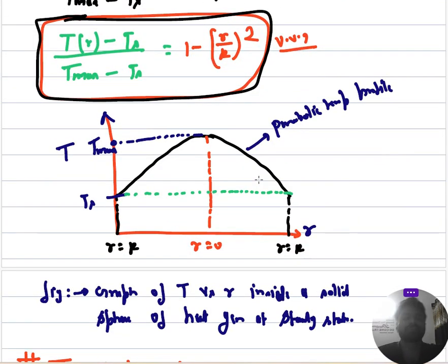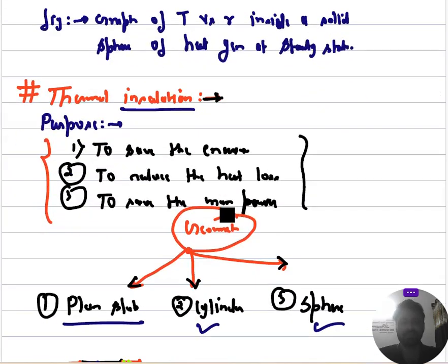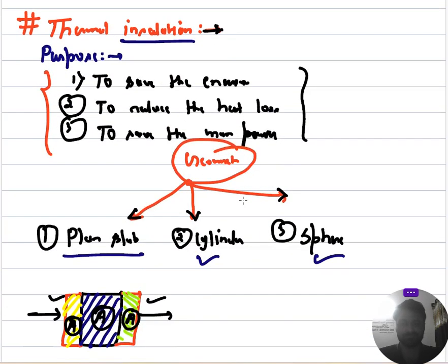Okay, so after that, sometimes you can calculate the maximum temperature also, because if there is heat generation inside the solid, what will be the maximum temperature? You can also calculate that. So the maximum temperature can be observed here at r equals to 0, at the center of the sphere, and the temperature will drop. Due to this, you can assume that there will be spherical symmetrical conditions, that at r equals to 0, at the center of the sphere, dT by dr equals to 0, that is the symmetric boundary condition that I already discussed in the previous slide.